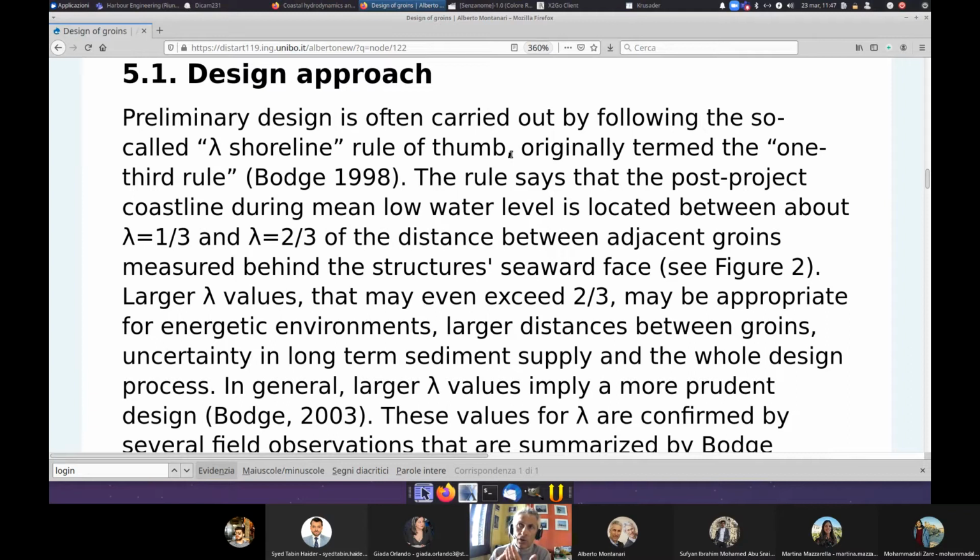Of course, it's not always possible, but with beach structures, it is possible, because these are usually not hard interventions, unless you design a seawall, which is not flexible. But if you design breakwaters or groins, for instance, you may make them partially submerged.